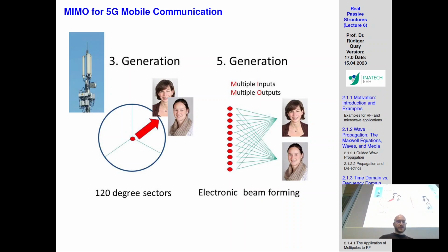That is the application of these modern antennas, of why we move into arrays: not only the aperture but also the ability to have MIMO, multiple input, multiple output. What does MIMO mean? Well, instead of having a 64 array construct so that you try to reach as many people as possible, you have 8x8 constructs, and these 8x8 constructs can always be superimposed into each other, so that you can span a virtual array, more cost-effective.